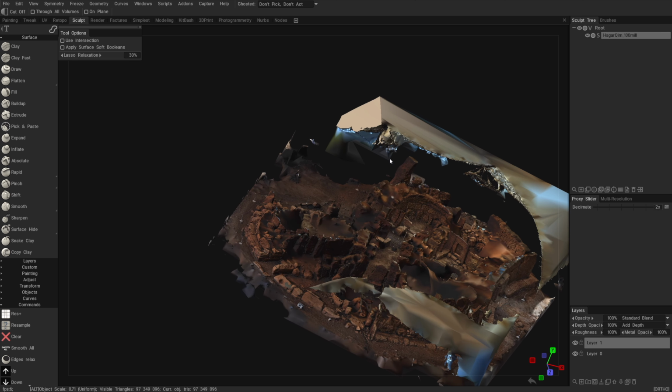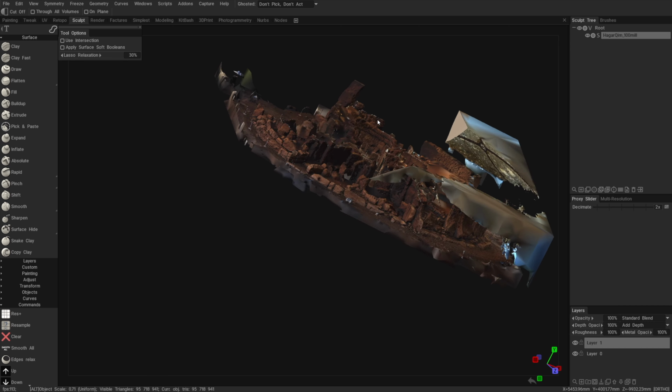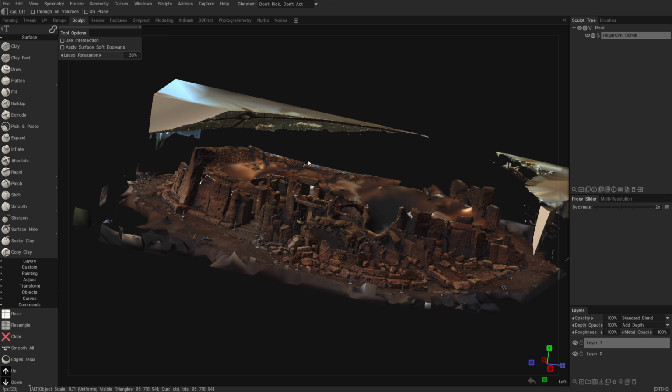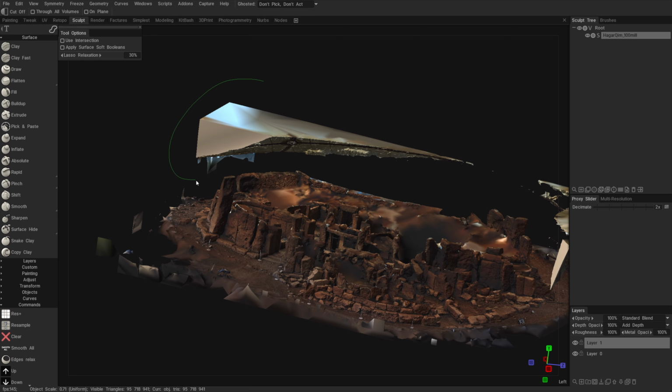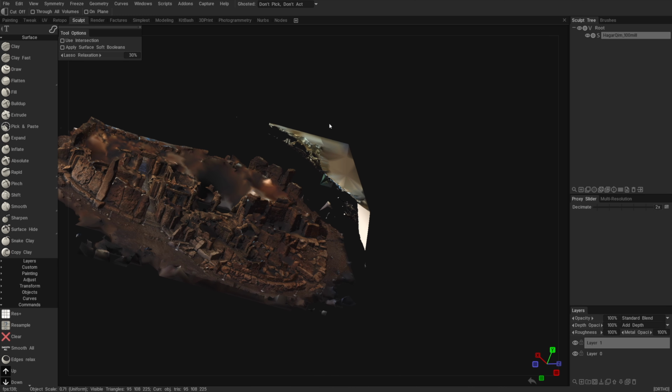Operating in surface mode is a lot slower than operating in volumetric mode, but it still works. And also it's more prone to errors, so you might have to backtrack because it does a Boolean shape, and if the polygons are weird, you're going to get a strange Boolean shape or a strange cut of the Boolean. So that's why I like to go over to voxels, because there are never any errors with the voxels. So let's quickly trim off these pieces here.